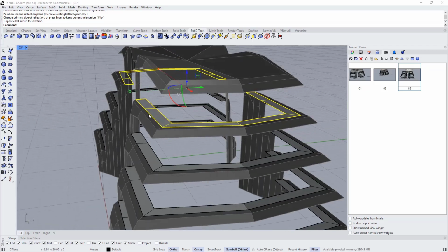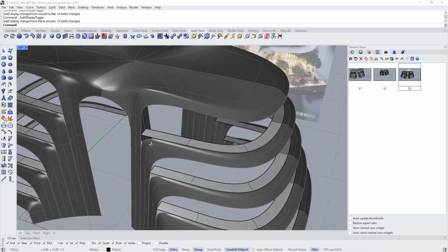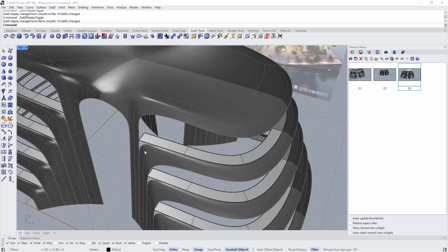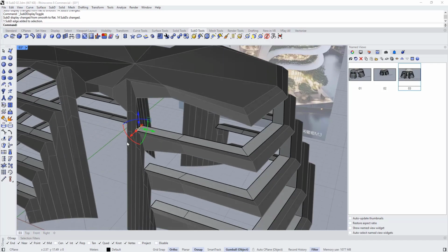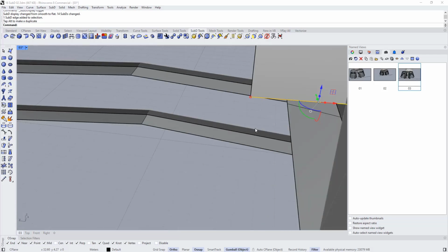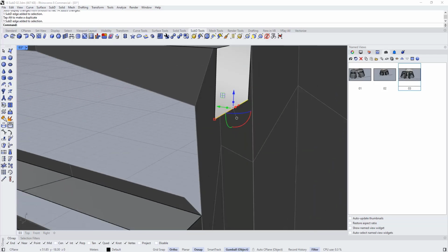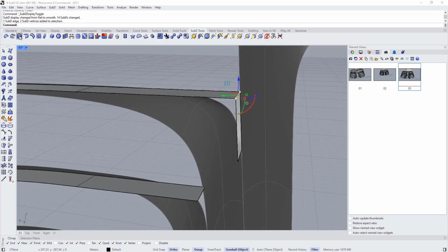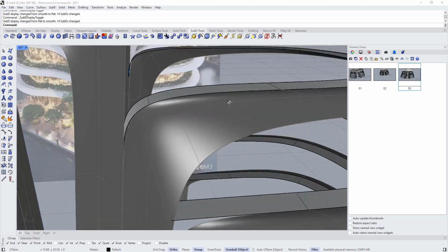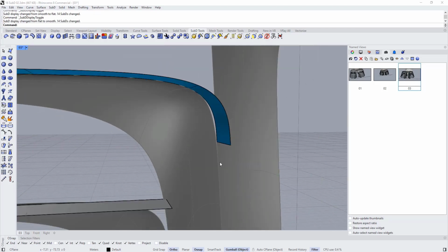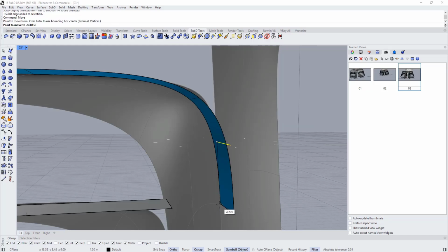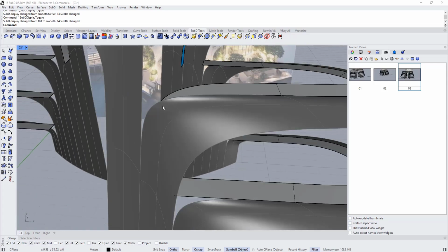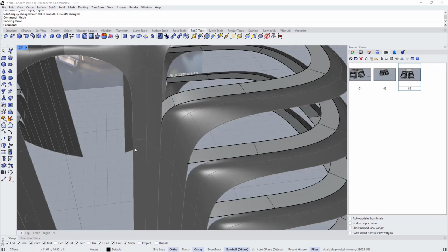So now we need to connect these two floors together. But I want to see what we can do with this connection. So what if I select this one and maybe extrude it, something like this. And let's align, hold Control Shift, select this edge and type move. Let's align it here, maybe something like this. Let's hold Control Shift, select this one and convert it into soft. Control Shift again, and let's move this maybe here. I'm trying to get some kind of soft connection here.